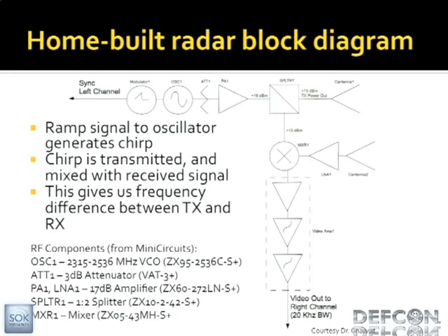I'll try to go through it and explain what's happening here. So the first thing is the thing that says modular, that little spike thing, that's the ramp generator. It's generating just a ramp in voltage, which gets fed to this thing with the curvy line called a voltage-controlled oscillator. And it does exactly what you think. The frequency of oscillation is related to the input voltage.